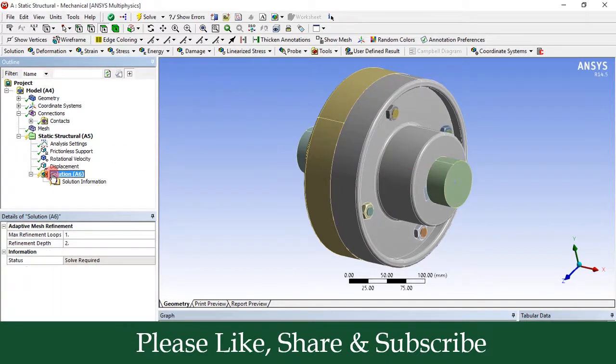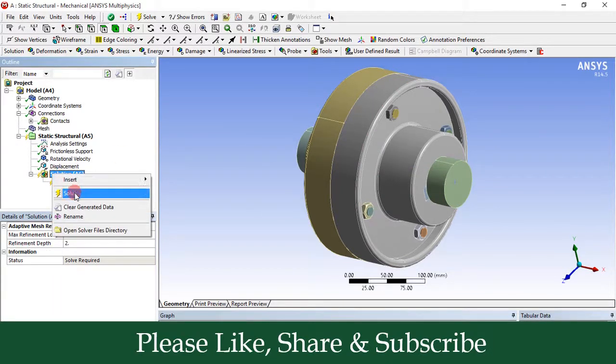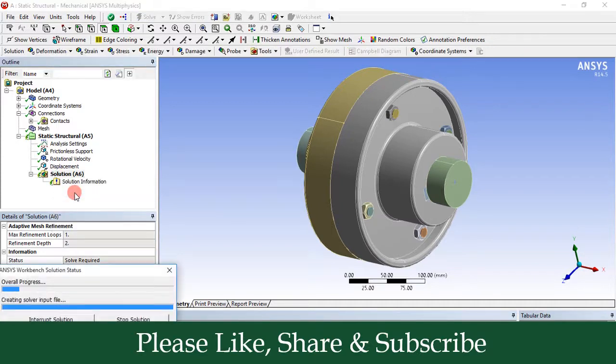Now right click on this solution and click on solve button. So it will take some time for the solution. Now once we get the solution, we are going to check the overall result for this rigid coupling. Remember that here we have applied the rotational velocity on the input shaft, so whole coupling is subjected to shear stress. So we are going to check the shear stress in this coupling.